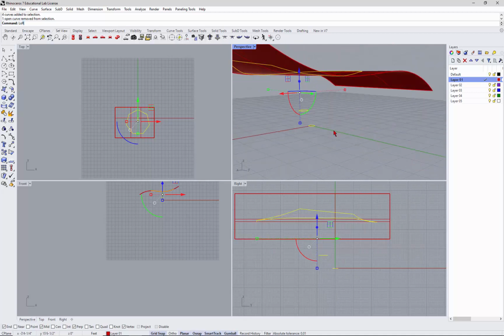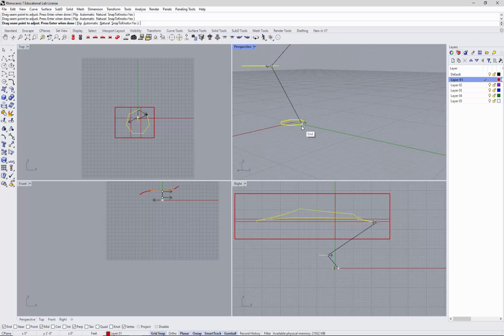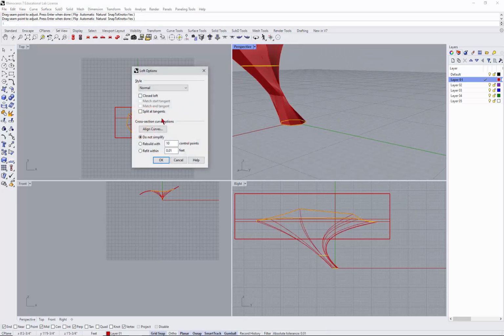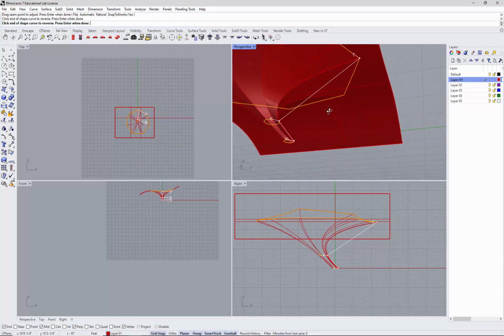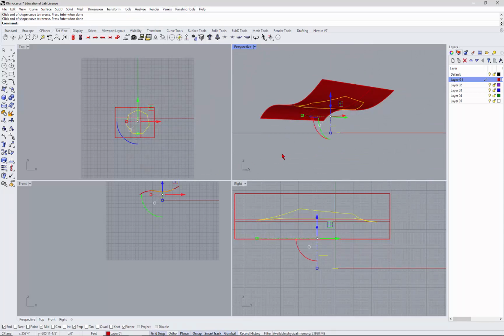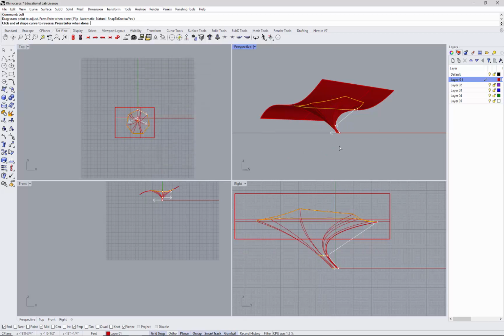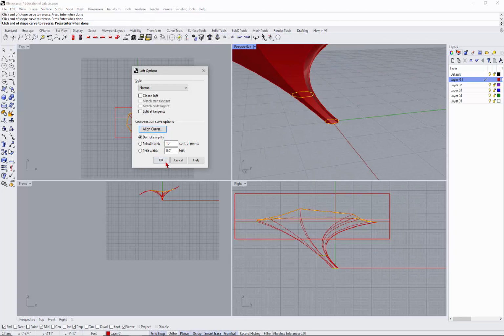And then you can type loft. Right? Let's go ahead and flip this one again. Whoops, no. Just flip it. Well, let's let it twist, right? And then we'll align the curve this one, right? And so now, right, I have a loft. Whoops. Align the curve over here, get that untwisted, and then enter, and then OK.